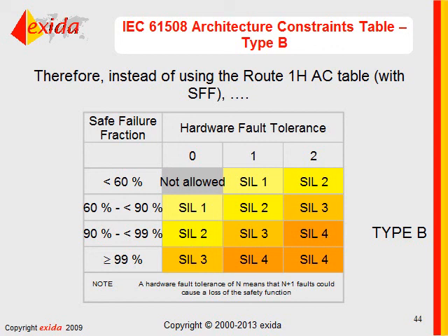For example, if I have a SIL2 design and a pressure transmitter in combination with a remote seal, which is one element, and the safe failure fraction drops below 90, a single channel is only good for SIL1, even if that transmitter by itself has a 93% safe failure fraction and excellent onboard certified automatic diagnostics.